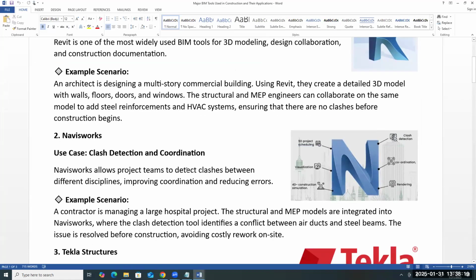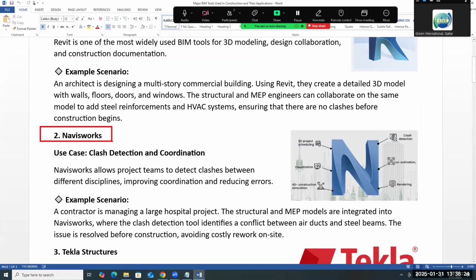In BIM, Revit is one of the portions, but other than that, there are several other applications available, which is Navisworks. Navisworks will help you to do the clash detection and coordination. You are not going to do any design work there. You will be exporting your model from the Revit model to where? To Navisworks. There is nothing to design in Navisworks, only clash detection, addressing the problem